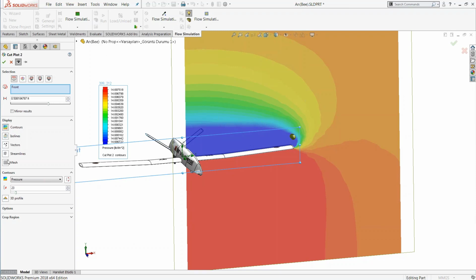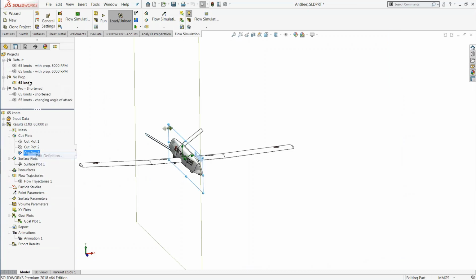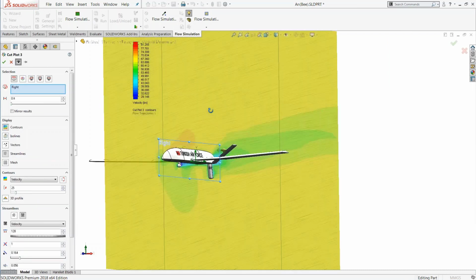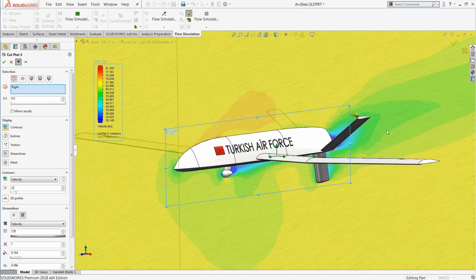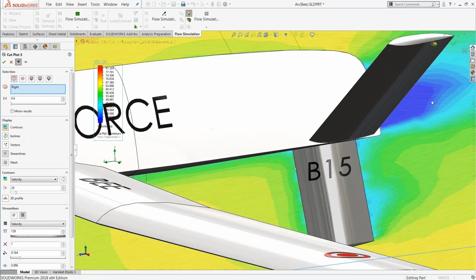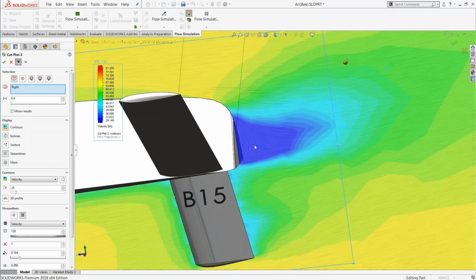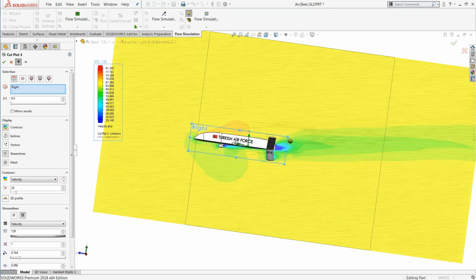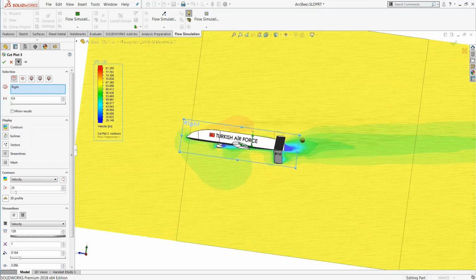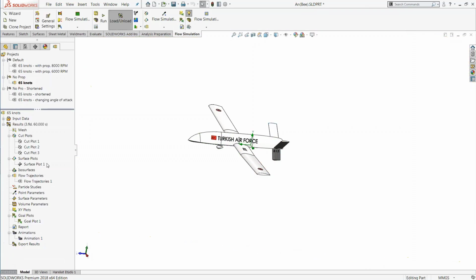We can look at all sorts of things in these plots, like, of course, the mesh or maybe the vectors of the flow. And some of these properties will be more interesting maybe from a side view. We could turn on things like the streamlines, which are dynamically drawn when we zoom in and out on the screen and help us see things like recirculation or eddies or vortices. So again, this is at the end of my simulation here where my aircraft has been pitched up 10 degrees or so. So here's the free stream velocity coming in. And of course, again, there's the flow separating. And if I were to drag this back and forth, I can see that over other areas of the model, like, for example, the wing.